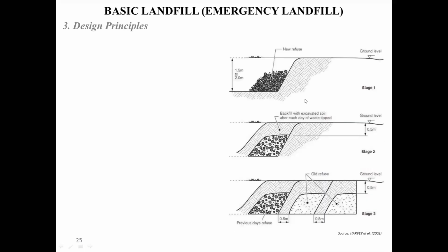Now you have basic landfills. Of course, all landfills have them, but they are supposed to be designed with some principles, or some basic necessities have to be taken. In your emergency landfill, or let us say you are going with the quick dumping of a landfill, these are the principles which you have to take into consideration. So it says that the pit should be backfilled with excavated soil every day.